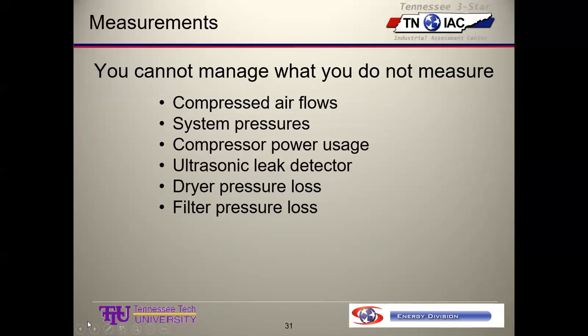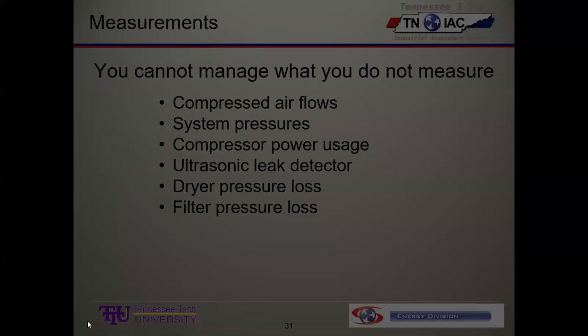And we want to be able to monitor all of the components in the system because it's possible for them to get clogged up with debris or crud and increase the pressure drop significantly. And so the usual response to that is to up the discharge pressure on the compressor, which then increases the power bill even more than it was before.